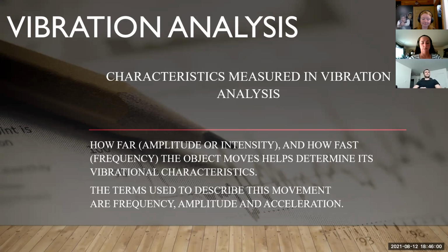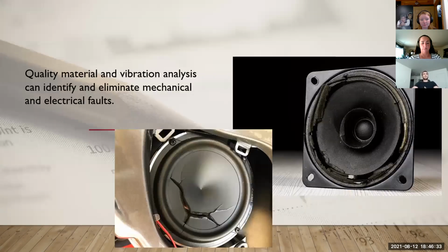Vibrational analysis is the process of measuring the vibration levels, patterns, and frequencies of a device to detect any abnormal vibrations that can affect the overall condition and function of a device, which may cause future issues or failures. Finding and fixing these issues early in the design phase has the potential of increasing a product's overall quality. Doing a vibrational analysis can increase the ability to find and use the lowest cost parts that can handle the vibrational abuse while ensuring the quality and longevity of the product are built as designed.